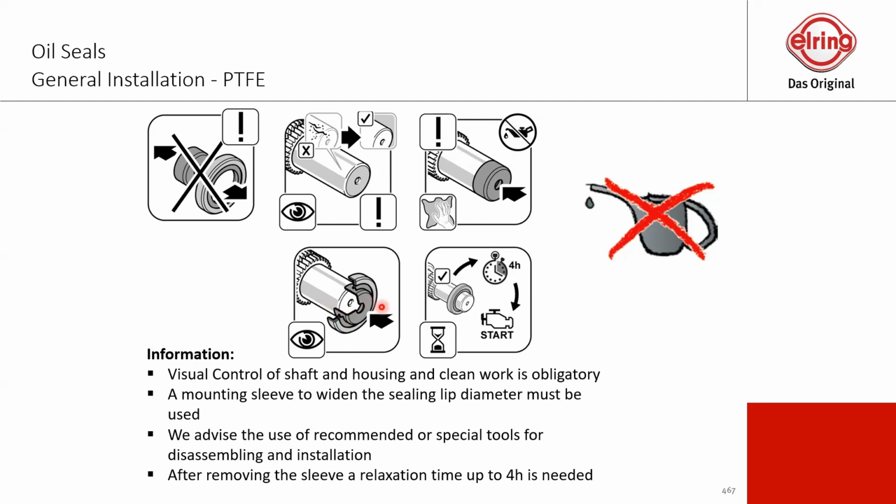Then put your oil seal evenly over the shaft with your mounting tool. It's very important. And now comes the point: you have to wait 4 hours until you start up the engine. So now comes the question, why do you have to wait? Because if you check this PTFE lip, it is a very stiff material, and the material itself is self-morphing, so it morphs back into the shape it was. But morphing back into the shape takes time.